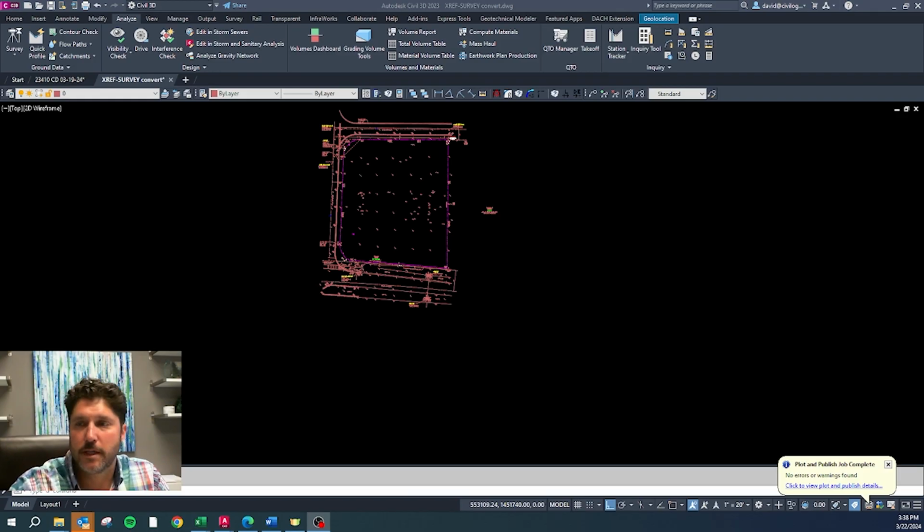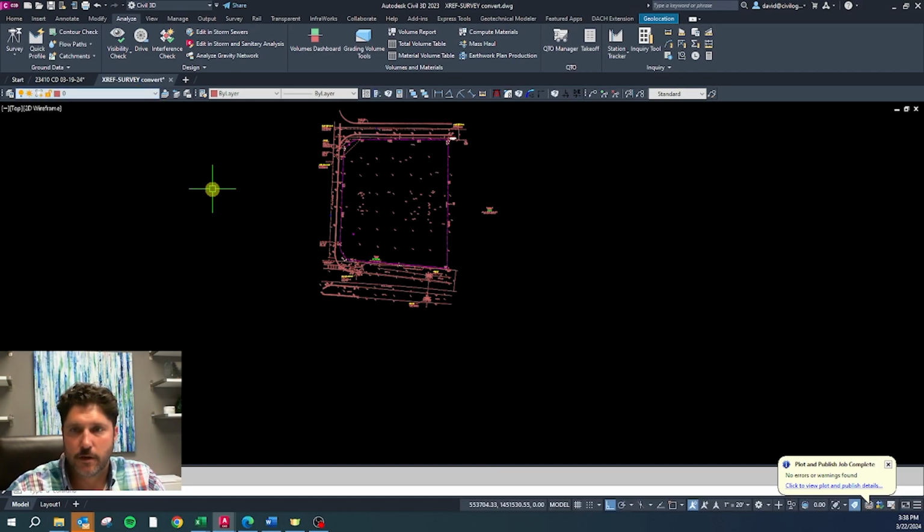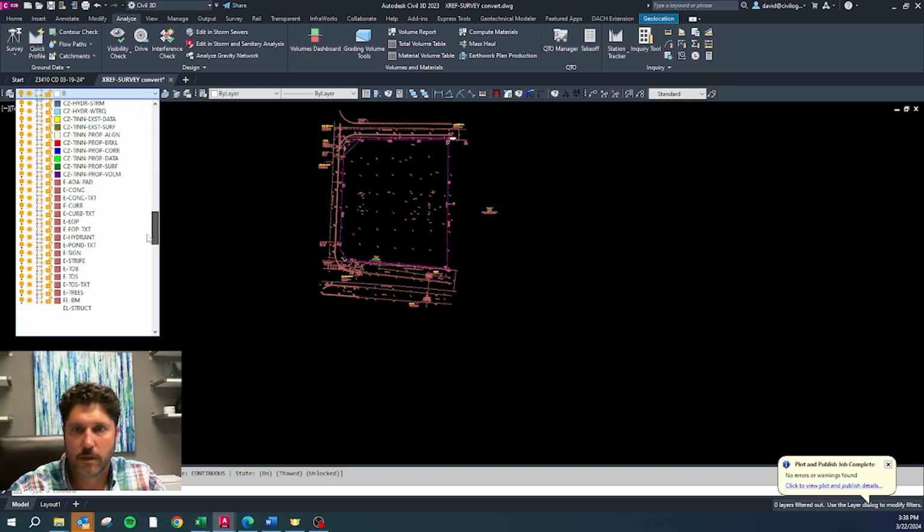Good afternoon. In this short episode, I'm going to show you how to convert a survey. You can see here we have the surveyor's layers. We're going to run the command civlay and type F for full, and that will load our layers in here.